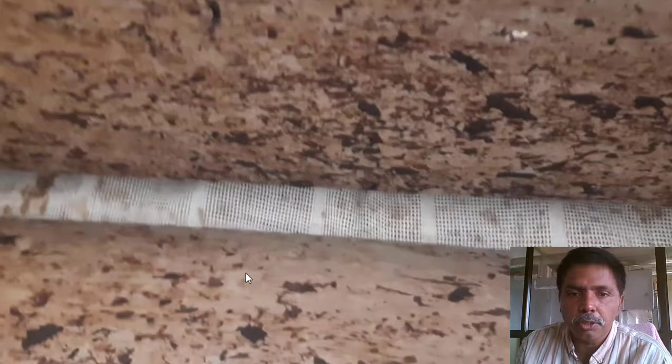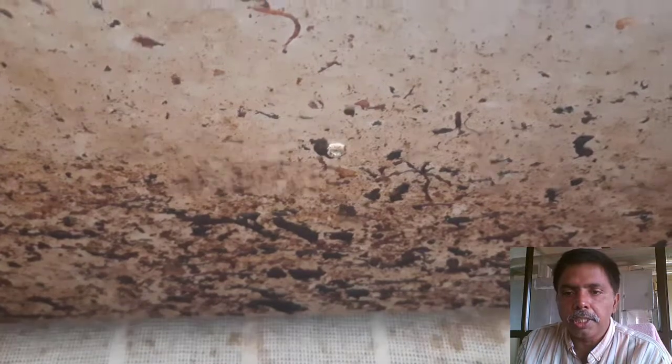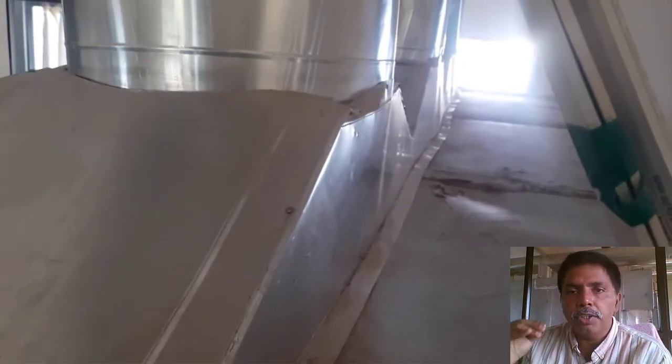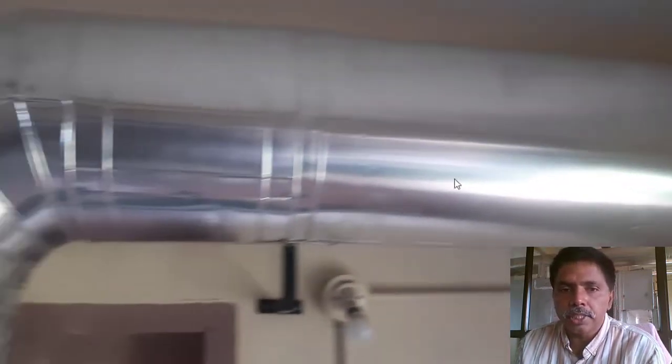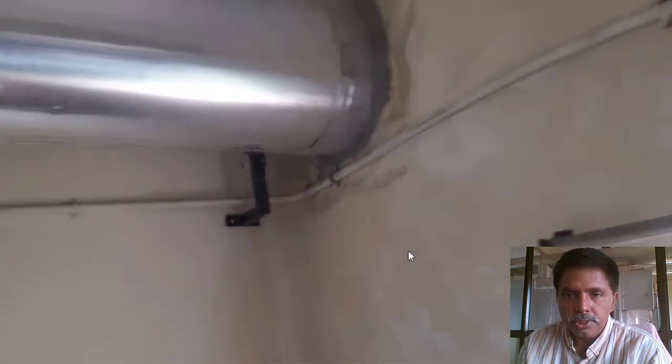This is the loading, top side loading we are doing upon the conveyor belt. After that, humid air comes through this duct to the blower. If relative humidity is high, we exhaust to the environment. If relative humidity is low, then we recycle the air. At that time we are storing the solar energy. The main advantage of this system is that we are separating heating and drying. Generally in solar dryers, heating and drying are not separated. This is the duct, you can see.